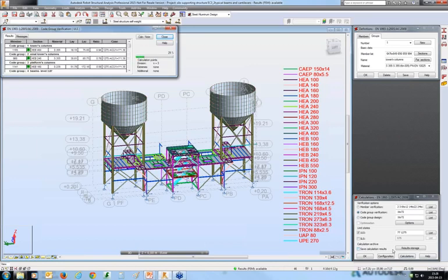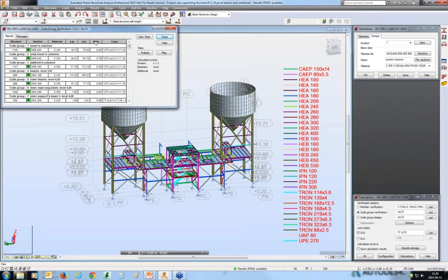As I change the sections that influence the set of forces, the sections chosen initially for a different set of forces may be wrong, and usually this is true. Let me sort by ratio. It's okay, we have like three groups that we need to focus on. So I'm going to design these three groups, not all, but the ones that failed, which are 12, and then 69, and last is 42.